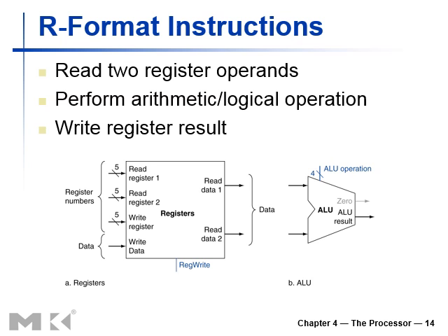Then we've got some register files here. Register file basically is a compartment that provides us the content of the registers that are being included or being utilized in the instruction itself. So these are the interfaces for the register file. This is a control line basically that has been generated by the control unit. Then we've got read register 1, read register 2, write register, and write data.